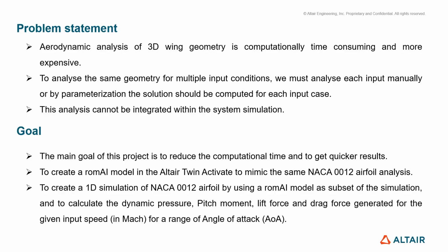And the goal of my project, my main goal here, was simple: find a way to give this result much faster. I wanted to create a fast, predictive AI model in Altair Twin Activate that could mimic this complex analysis. The final plan was to use this AI model in a simple 1D simulation to get key results like lift, drag, and pitch moment almost instantly.